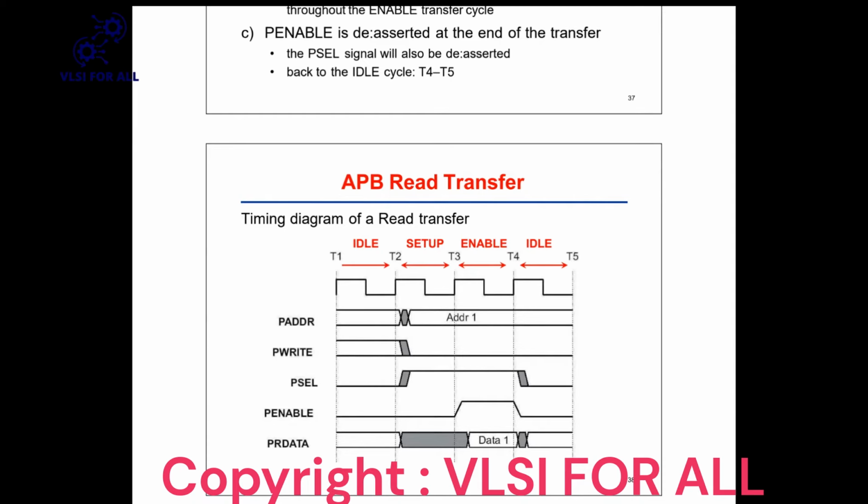Did you get this cleared? Or is anyone having doubt between read and write transfer? Forget about with and without wait state. That ready signal they haven't shown, so we will discuss later. But here the simple thing is that you can understand read and write transfer on the basis of the status of the write signal. If write is 1, then you have to perform the write operation. If write is 0, then you have to perform the read operation. So did you get this basic thing cleared?